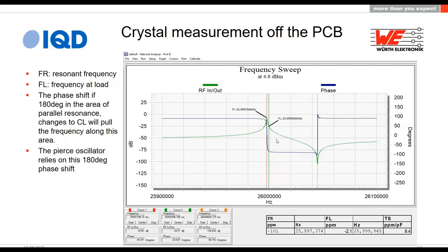So our oscillator circuit that we're using is called a Pierce oscillator circuit. It relies on an inverting buffer, and the crystal has to have a 180 degree phase shift itself. They combine to make 360 degree phase, and that's how we get our amplifier through. And that has quite a neat effect because it makes it much harder for frequencies that are outside of this range to be amplified. So I hope that slide puts some relevance to the numbers that we were looking at in the previous slide. That was my intention with this one.